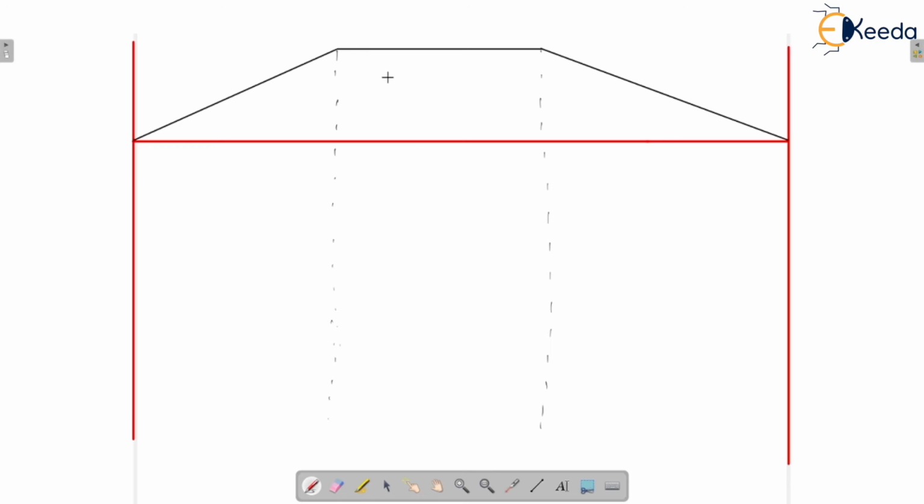So this is the displacement curve s, and this is theta. And this is 2 pi, the complete angle is 2 pi, because the follower reaches the initial condition during one complete rotation of the cam. Now let me draw the curve of the velocity. You just have to remember that the displacement curve is linear during the uniform velocity motion.